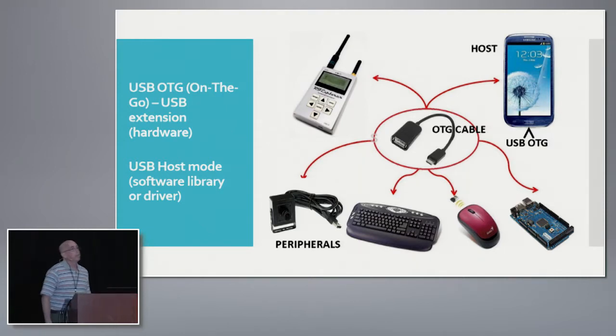USB host mode is more of a software thing. It's something that the operating system has to support. And these days, the latest versions of Android support USB host mode. It's something that Google feels is a critical feature. So going forward, most Android devices will support USB host mode. Not all hardware vendors support OTG, and it's a matter of cost. But because Google thinks that USB host mode is so important, the most recent Android devices will support OTG.